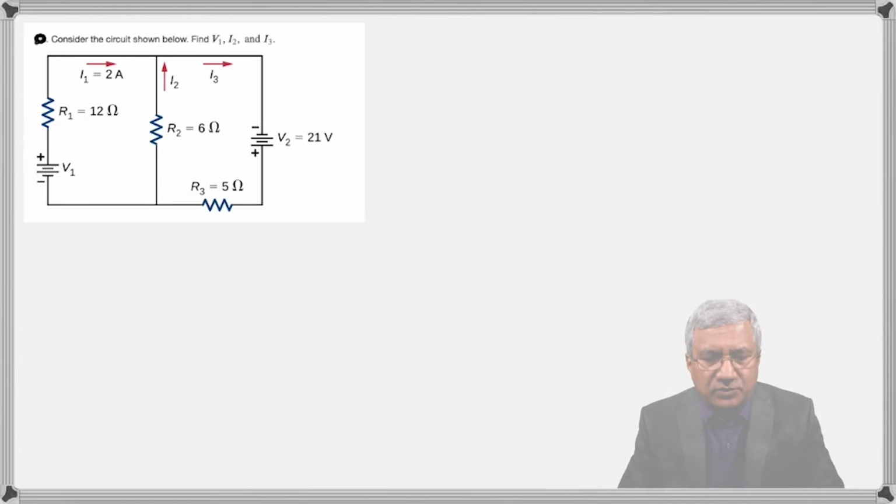All right, here is the next one. This is a circuit where we have to find the currents. And to find the currents in the circuit, we will have to use Kirchhoff's laws. Remember, there are two Kirchhoff's laws. One is the junction rule, and the other is the loop rule. In the junction rule, the total current flowing through any junction is zero. What does that mean? The currents coming in is equal to the currents going out.